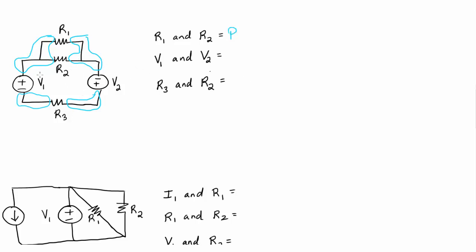V1 and V2, if you had some kind of current that was flowing in the circuit, if we say that it's going downwards over here, it goes down through V1, goes through R3, goes up here, and then it hits V2. So because the same current flows through V1 and V2, they're going to be in series. Okay, this was parallel, this was series.